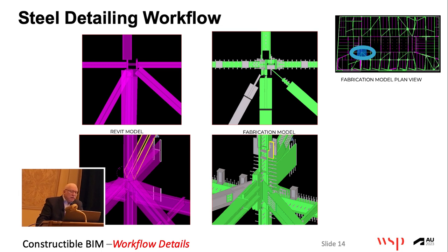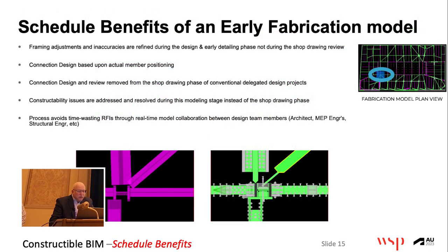I'll show it to you right here, for real occurrence. Here's the Revit model, here's the fabrication model. Now it's in 3D above and below the 2D. We had to move the working points to get it to be buildable. We had to go back and re-engineer the members because the connections could not all meet at the same point. I think I have a better view in the next shot. Here it is, a close-up. We had to move the working points.